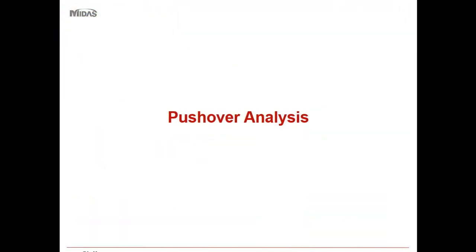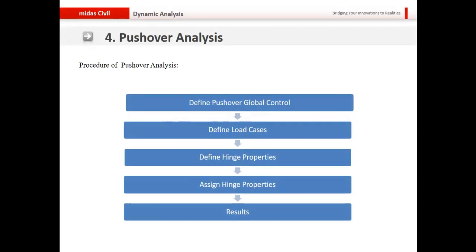Then in the program we have the pushover analysis, which is, as you might know, a static analysis that considers the nonlinearity of the structure. Basically what it does is you apply a lateral load, incremental lateral load that will generate certain force and deformation of the structure, and then from there you can obtain its behavior, which will be simulated during the earthquake.